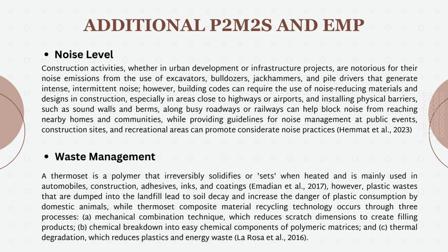This slide discusses two additional environmental protection measures and management plans, which are noise level and waste management. For noise level, it mentions that construction activities like excavation, bulldozing, and pile driving generate significant noise, especially in urban areas or near highways and airports. Potential mitigation measures highlighted include using noise reduction materials and designs, installing physical barriers like sound walls, and providing guidelines for noise management at public events and recreational sites.